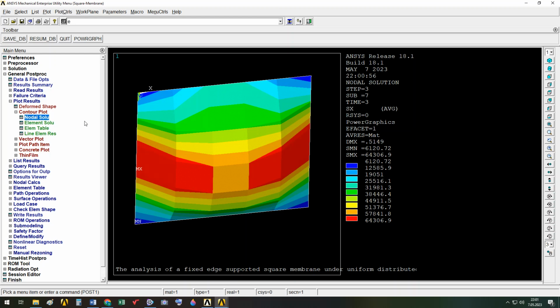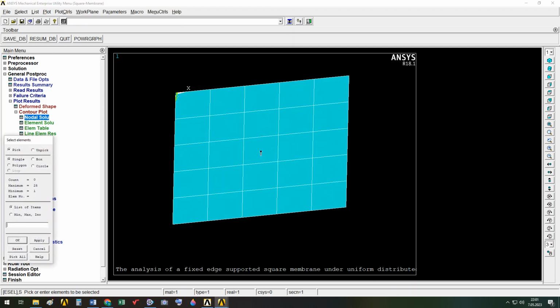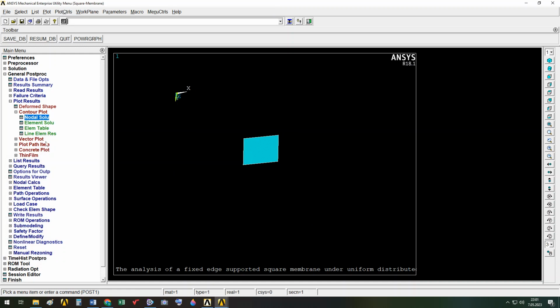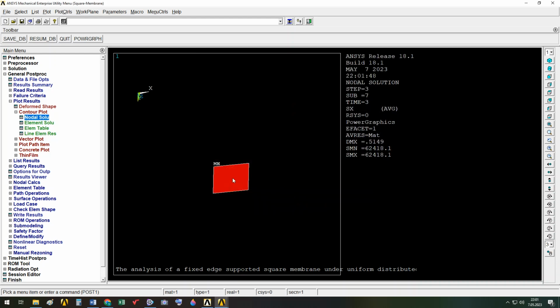As a result, you plot and element select, a new set using graphical technique. This is the element in which the midpoint is located. I select this, say okay. Here I write plot. I see only this element. Since just this element is selected and kept in memory, when I click here and want to see the stress result, I will see the stress results of the element that includes the midpoint.